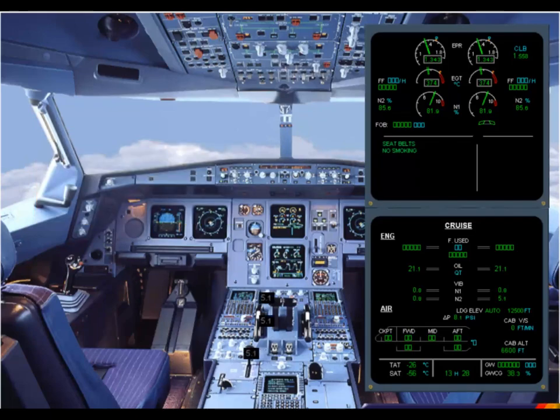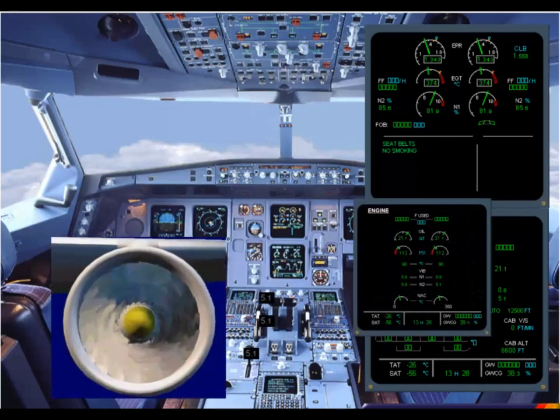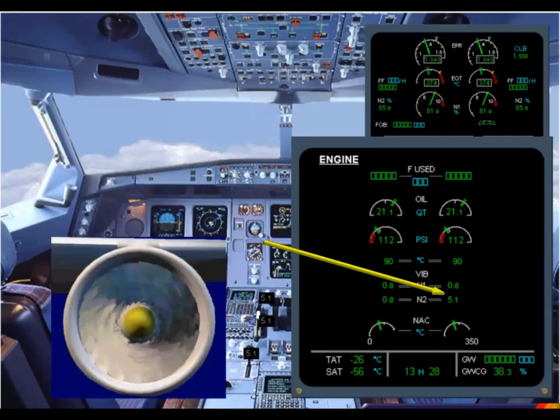If a system parameter, for example an engine vibration level, approaches a limit, the ECAM system will advise you of this by displaying the relevant system page on the system display. The affected parameter will pulse. Notice that at this stage the parameter is still shown in green since it is still within normal limits. This is known as an ECAM advisory.